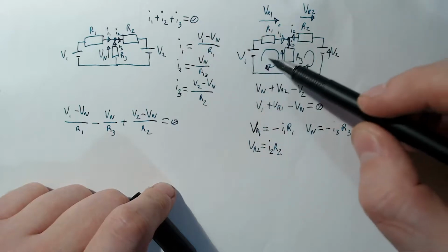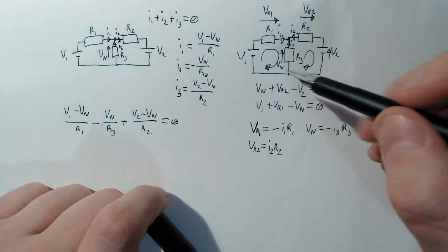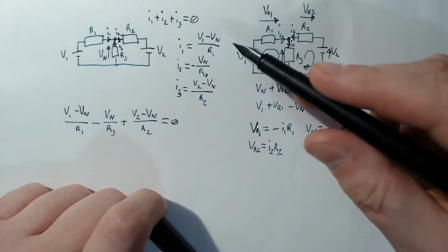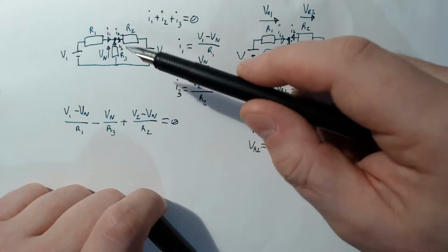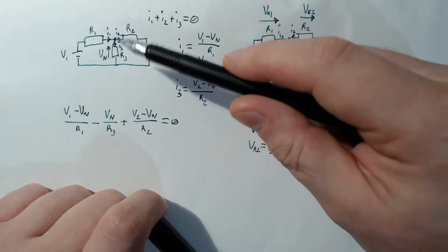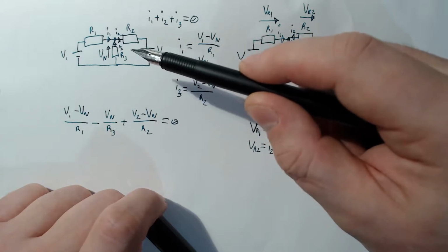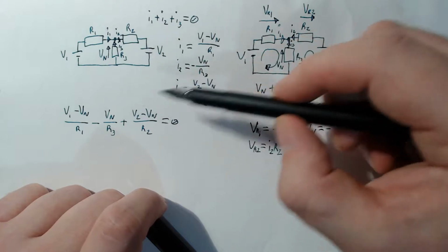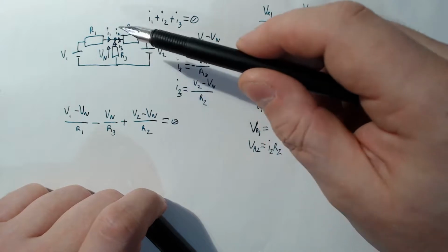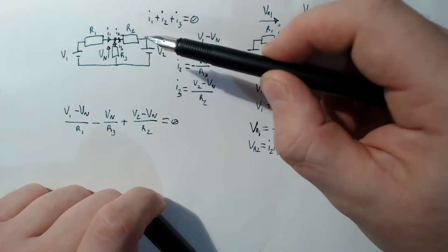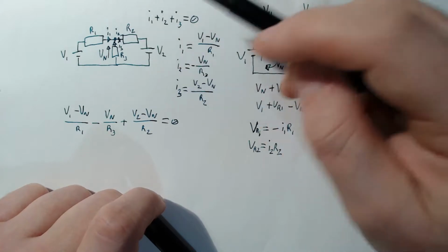Now you might think just because this is Kirchhoff loop analysis and we're mostly using Kirchhoff's voltage law, we also need Kirchhoff's current law, and we actually had that in this one. Although we were using nodal analysis and Kirchhoff's current law mostly, we made some implicit assumptions about how the voltages sum to 0 here. When we formed these equations here, we said that if one voltage up here and one voltage here, the voltage drop across R2 must be Vn minus V2.